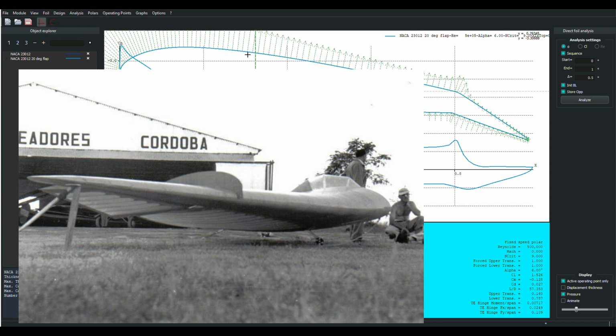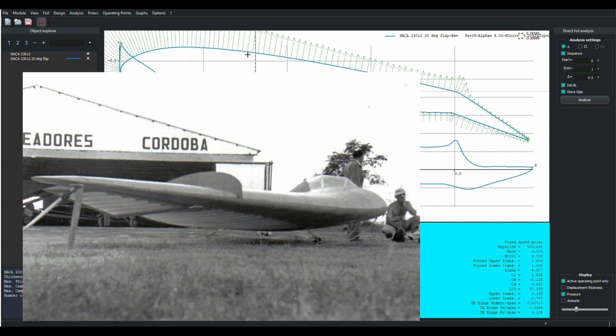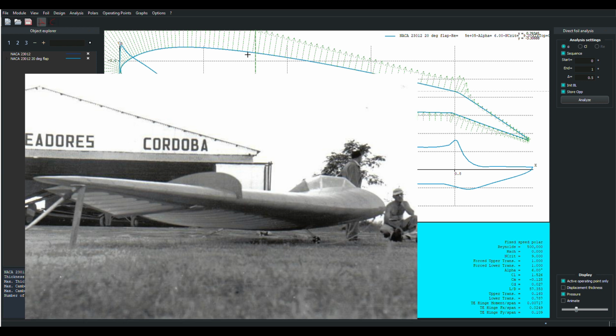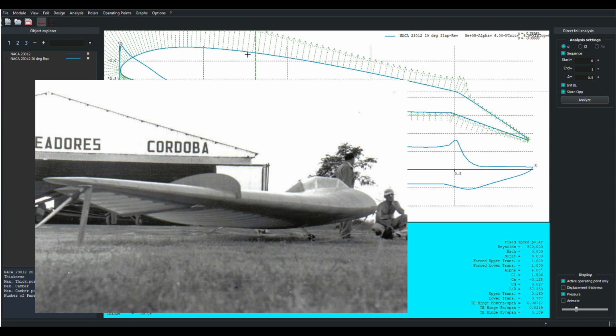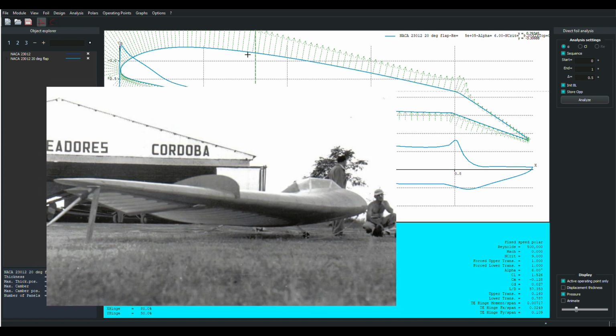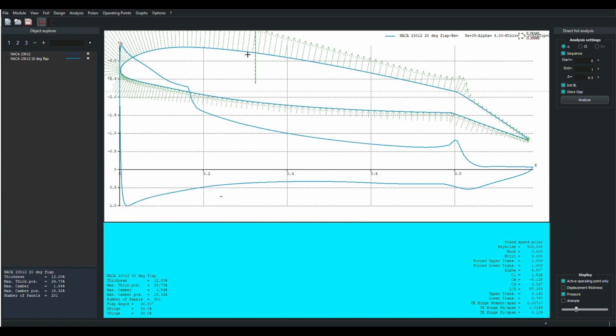You still got problems. You put a taller fence on there and a taller, until that fence becomes a significant percentage of the half span of the aircraft, because then you're dealing with the potential flow field. And in my particular case, that's like at least 3 feet tall. And these fences that we see on this glider are nowhere near a significant percentage of the half span. So they're trying to fix a problem and failing. And it's because they hadn't wrapped their brains around it. They're not dealing with a boundary layer problem, they're dealing with a potential flow field problem.